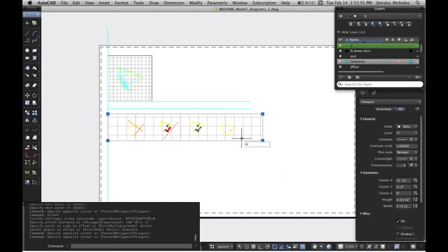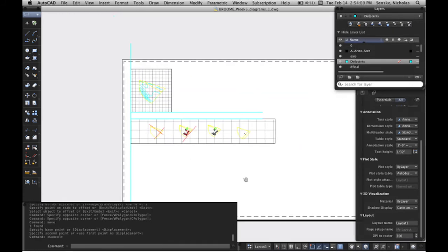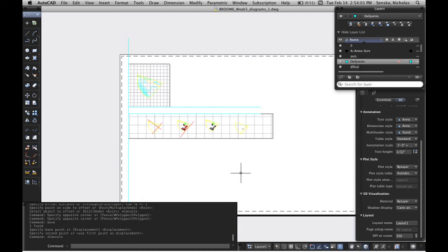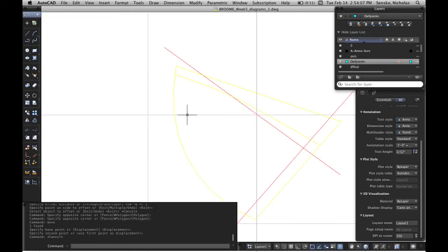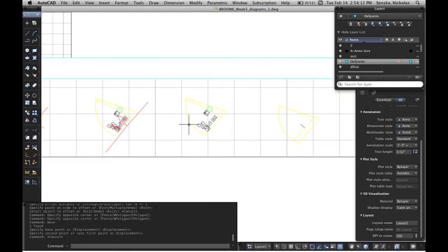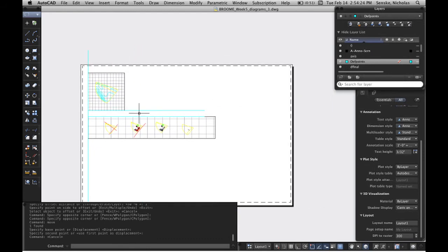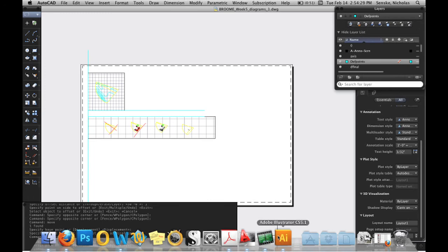So then I can take this thing. And now if I wanted 1 inch of white space, it's very easy for me. I think it's hard to do in Illustrator. Yeah. This is how people lay stuff out in AutoCAD. But again, I don't think what you'd want to do is do 4 windows for each of these things and then try to align them. I think you'd want to do that in AutoCAD and model space first. Get them all aligned to each other, snap them all to a guideline, maybe a def point line, then pop these into your layout. So you do all your layout stuff, guys, in this, and this is how you get your different scales. Okay? Then let's go to Illustrator.